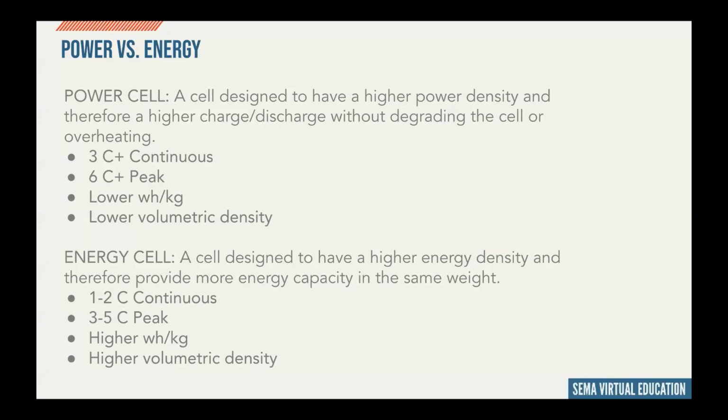It also typically has lower energy density, right around 120 to 200 watt hours per kilogram, and lower volumetric density, which means that to have the same capacity, a power cell will take much more volumetric space. A battery pack at 80 kilowatt hours will be much bigger in physical size than one built from energy cells, with their higher energy density and higher volumetric density.